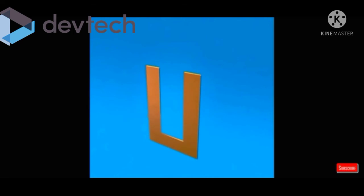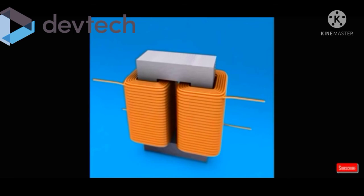The thickness of these laminations varies between 0.25 mm to 0.5 mm, and as steel is a conductor, the laminations are electrically insulated from each other by a very thin coating of insulating varnish or by the use of an oxide layer on the surface.